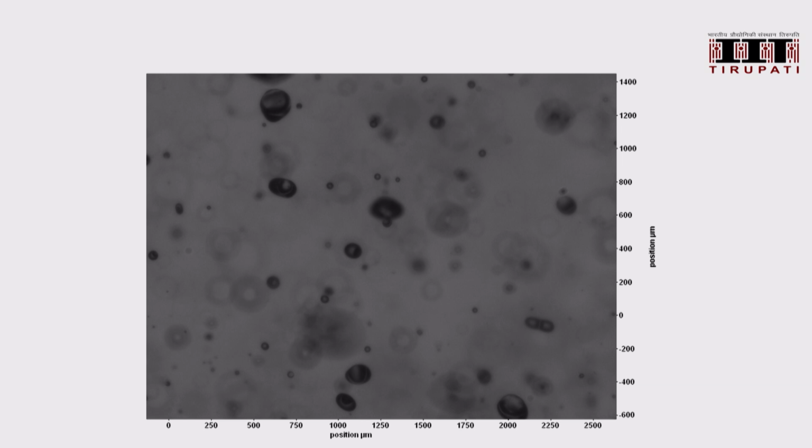I'm viewing this area, how much length it is. That's it, right? How much distance it is. And how many pixels, because the camera sensor will have a certain number of pixels. So imagine this is 1000 pixels, say 1000, 2000. Let's say 1000 pixels is 2 millimeters. So each pixel will be 2 micrometers, right?